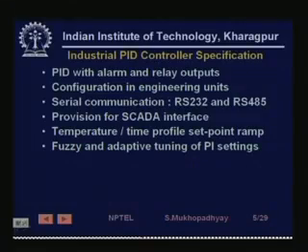So, in such cases, for efficient response as well as for things like energy efficiency, you need to tune PID controllers from time to time, and so they have provided algorithms for doing that using fuzzy set theory, which is a special technique used to design controllers. So, you can have fuzzy and adaptive tuning. Adaptive tuning means that the controller continuously keeps adapting as the plant changes. So, you could choose one of these to get the PID settings.